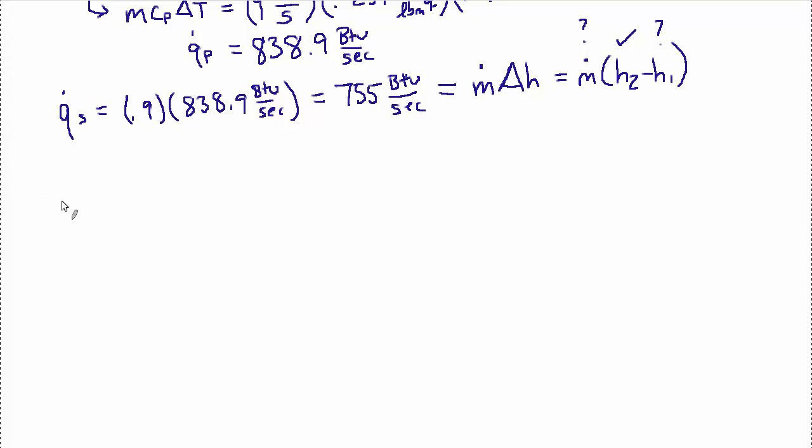We do know states 2 and 3, so let's talk about state 4. So we're going to make an assumption for the pump. On the output of the condenser, which is the inlet to the pump, we'll assume that all the steam condenses. So if all the steam condenses, then the quality of the input to the pump is 0, which is to say it's a liquid. And it really has to be. The reason we can make this assumption is because the pump can only pump liquid. So this is a fair assumption. I wasn't sure if I could make it because after the turbine I was kind of thinking maybe we had to use the entropy there and we had to interpolate and all that. But I think it's a pretty fair assumption for the pump.